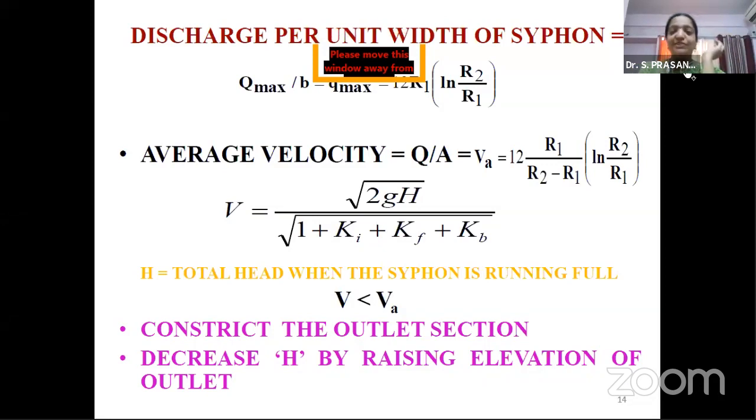Even I had this question when I was starting my work. Actually, K omega and K epsilon both are two equation models. And both have the same constraint in the sense that dissipation rate there is epsilon, here it is omega. But it is going to solve the kinetic energy first. So whenever we do analysis, we start normally with K epsilon. K epsilon is the most widely adopted model. That is the first model which you have to use for your analysis.